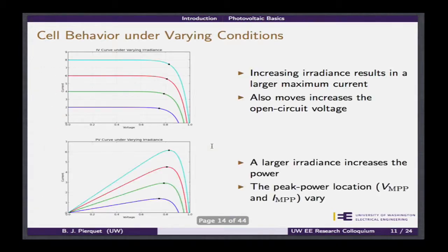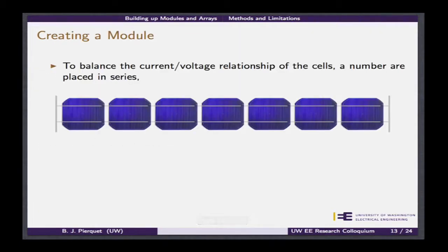On the top, there's metallization that connects across and over, and it connects to the one right below it. And so it's essentially series stacked, one on top of the other, in order to get the bottom terminal underneath connected to the top terminal of the next one. So simple ribbon connections soldered to the tops of the cells, and they just pile these up to make nice little strings.